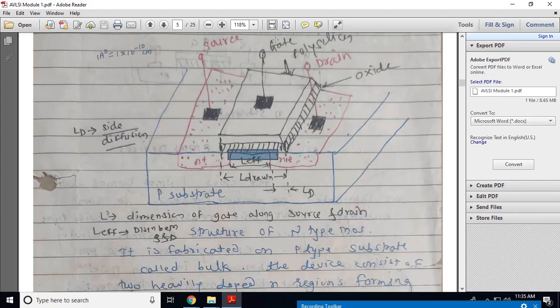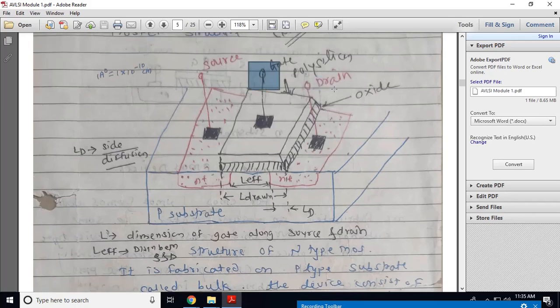When we apply a positive voltage on the gate, electrons enter this region and try to move towards the drain, and drain current starts to flow in the MOSFET. The source is a supplier which provides the electrons, and the drain is a collector which collects them. Electrons move from source to drain when you apply the proper voltage on the gate and drain terminal. For the NMOS, we apply a positive voltage on the gate and connect the drain terminal to the positive terminal of the supply.